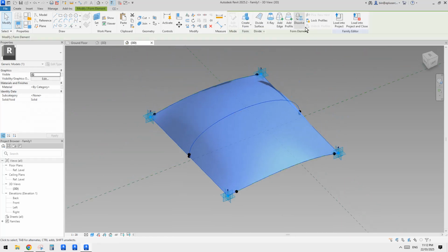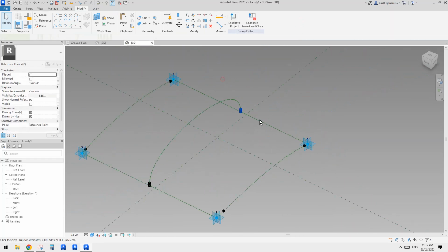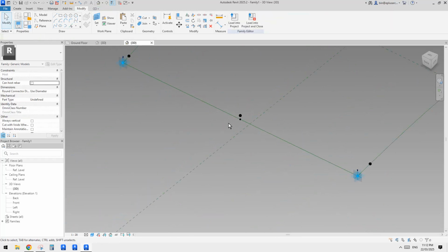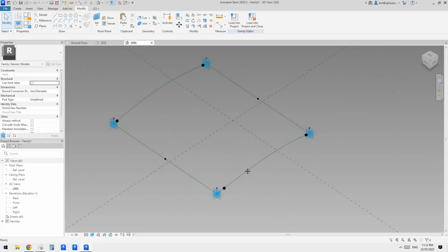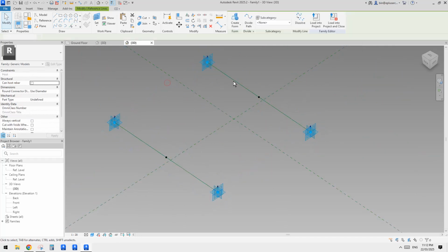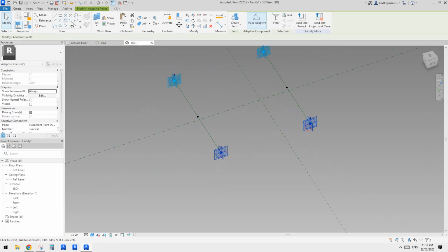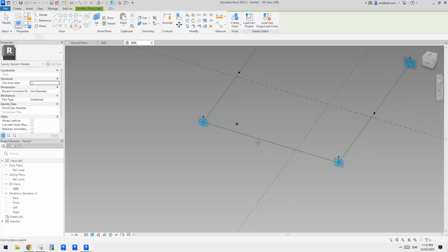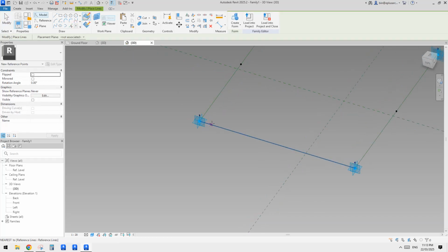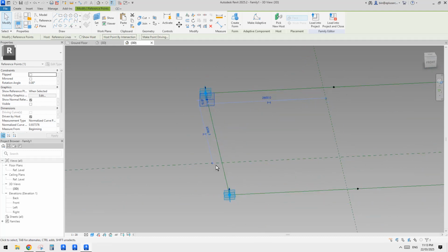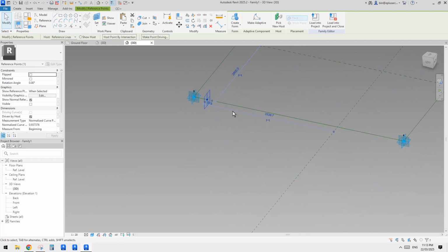So what we can do is, let's just dissolve this one, dissolve this as well, delete this. Maybe I'll just delete this one, and also delete this one. So we can just create a spline through points, and then use draw on face, which means it will always align with this. So it's more reliable, right?